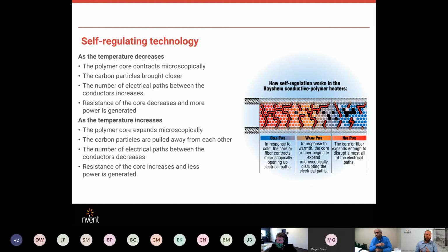A lot of times what I will see is that people say, okay, I have a safety shower system. I want very high reliability. I just don't want it to freeze. We've got to keep these things flowing at all times. So they'll try to pull the control and monitoring system, whether it's a thermostat or electronic controller, out of the scenario to increase reliability. That makes sense in that if you have fewer parts, there are fewer points of failure, and you have a more reliable system.